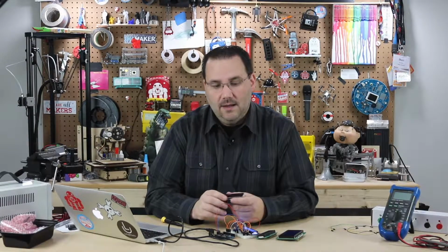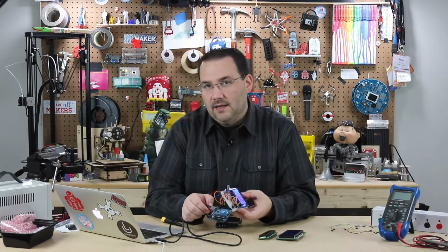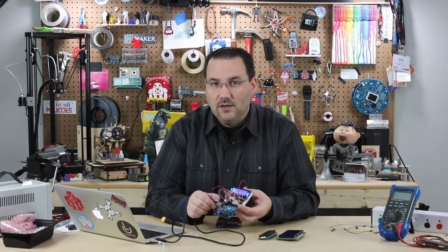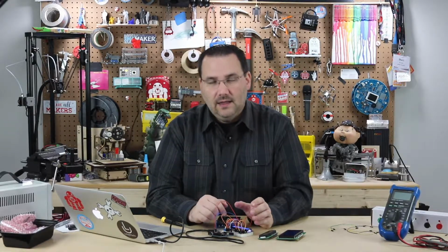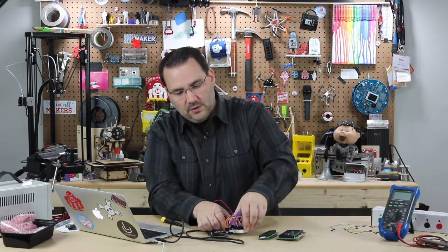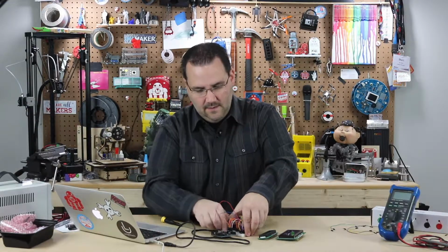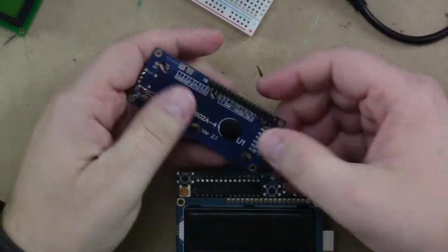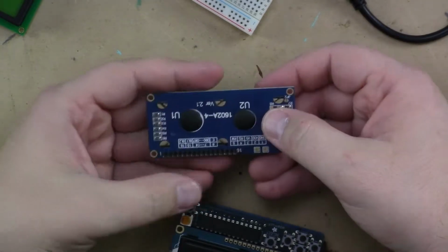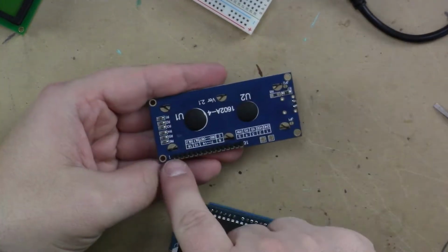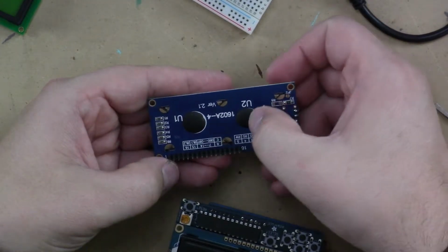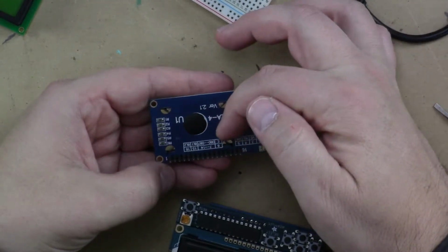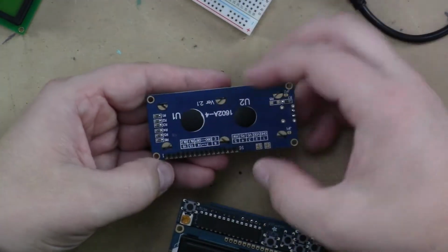There's a lot in this little package right here, and they're not very expensive, and more importantly, it saves a great deal of time. Now that doesn't mean you can't buy one of these for about $10 and hook them up, and you can buy them almost anywhere. The only thing you need to know when you buy these is how they label the pins. On this particular one, let me unplug it. On the back, make sure when buying these, they are labeled. You can see this is pin 1, this is pin 16, and it's ground, VDD, all the way at RS, RW, and then all these pins, your backlight pins.